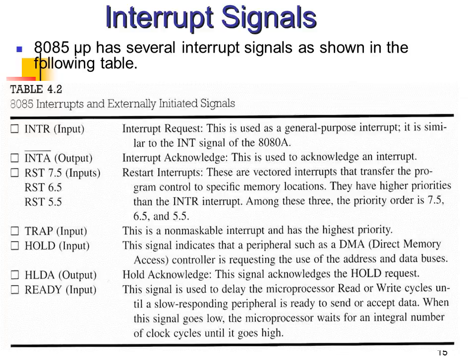READY is an input signal. The signal is used to delay the microprocessor read or write cycles until a slow responding peripheral is ready to send and accept data.